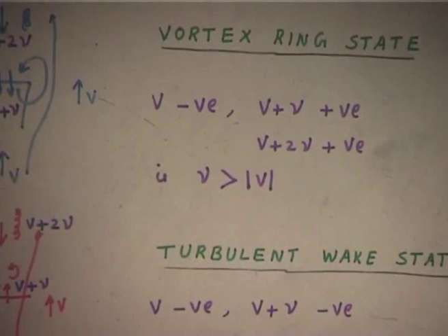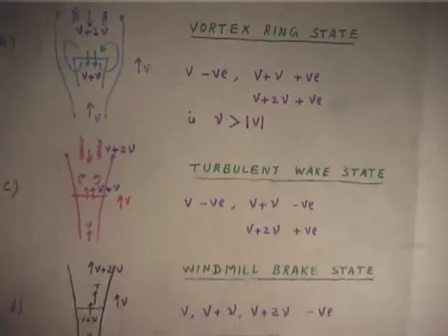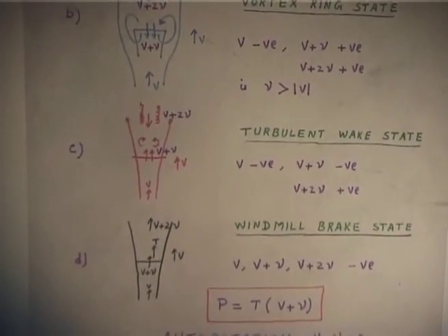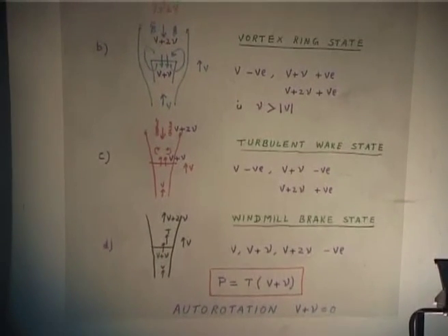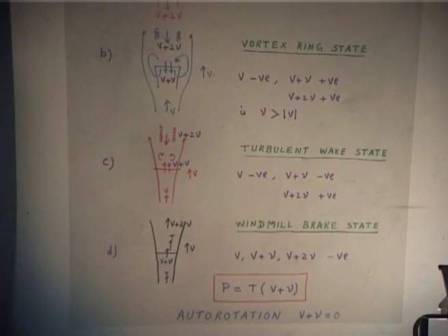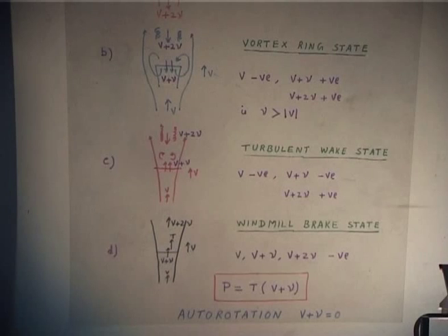Now, when V climb plus nu or V plus nu, that velocity term, is 0, that means my power is 0, but I am still supporting the weight. Please understand, power means the induced power. I do not supply any power, I do not require power, but I will be able to support my helicopter.